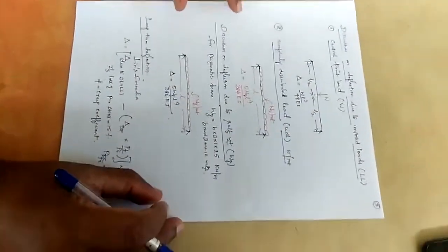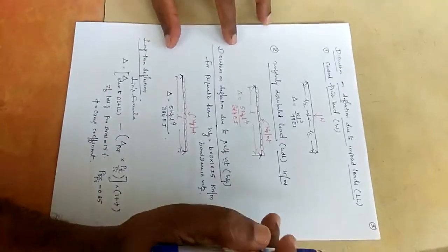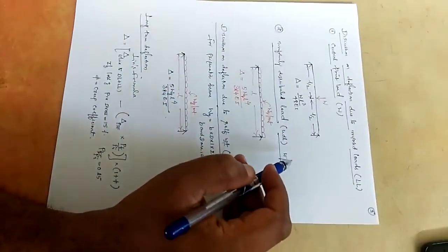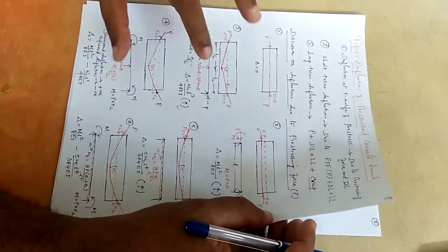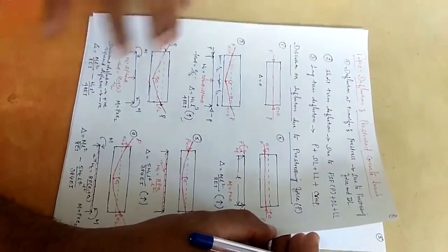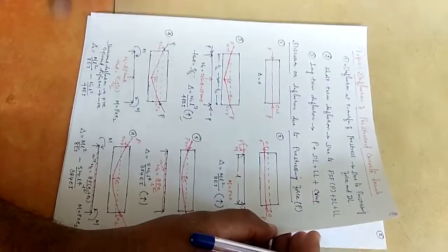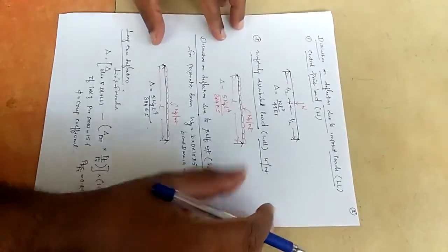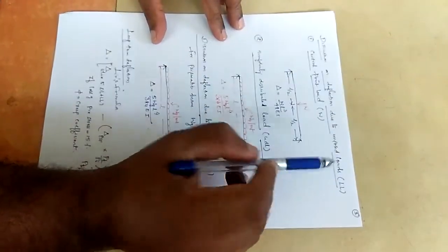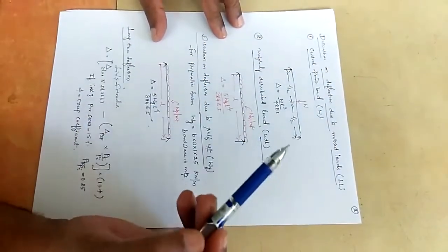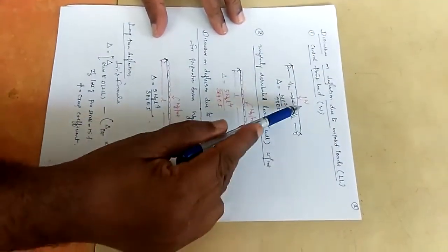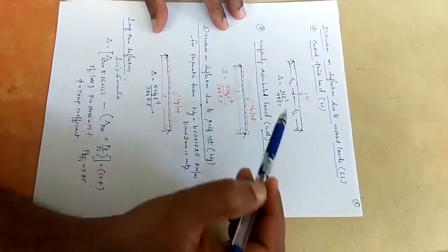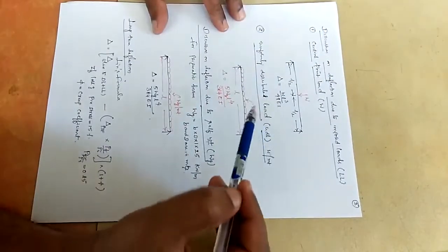That is about the discussion on deflection due to pre-stressing force. Actually that is very important because this is very new to you. The deflection due to self-weight and deflection due to live load you already studied in strength of materials. Deflection due to imposed loads, there are different types of imposed loads, but I am taking only two cases. One is central concentrated load, another one is UDL. You already studied in the previous discussion.